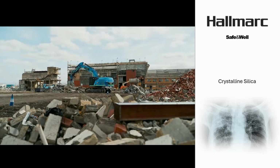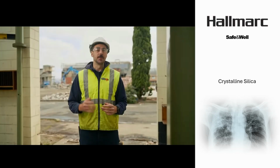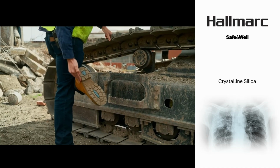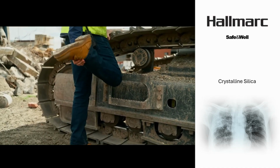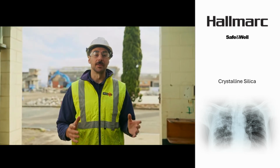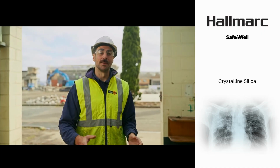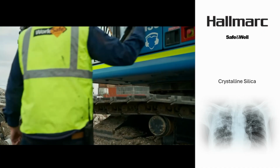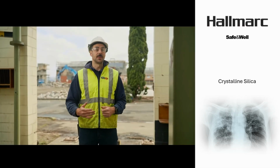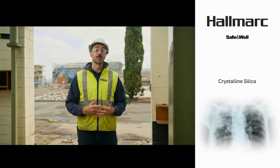Machines with enclosed filtered cabins are a great way to reduce exposure to silica dust. They do this by preventing dust from getting inside the cabin. Silica dust can also make its way into the cabin from your clothing or your shoes. Some machines are also fitted with a filter circulation system to remove dust from inside the cabin. When the machine is not in use, close all windows and doors to keep the dust from settling inside. Cabins need to be cleaned regularly, and filters need to be inspected and replaced to make sure controls remain effective.